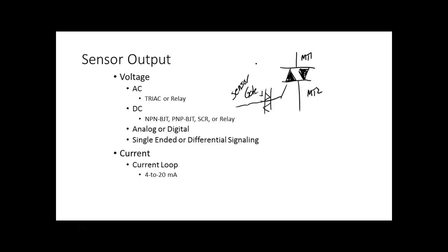A relay. Now, what advantage does solid state have over relays? What are relays? You've all had motor controls. These are electromechanical devices, right? And anytime you have an electromechanical device, that means what? It can fail mechanically or it can fail electrically. Another problem we have is that relays take time to switch from off to on. Solid state devices also take time to switch, but with relays we're talking milliseconds. Solid state devices, we're probably talking nanoseconds.